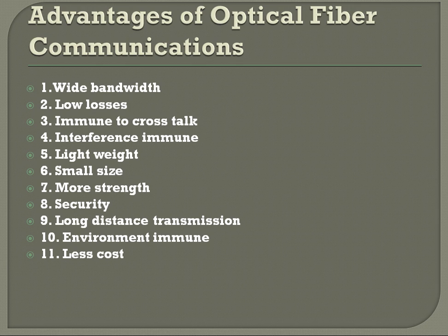The fiber optical cables offer very little signal attenuation over long distance. Typically, it is less than 1 decibel per kilometer. This enables longer distance between the repeaters. The third advantage is immunity to crosstalk. That means fiber optical cables have very high immunity to electromagnetic interference. Since the fiber optical cables are not conductors of electricity, they do not produce a magnetic field. Thus, the fiber optical cables are very immune to crosstalk between the cables caused by magnetic induction.